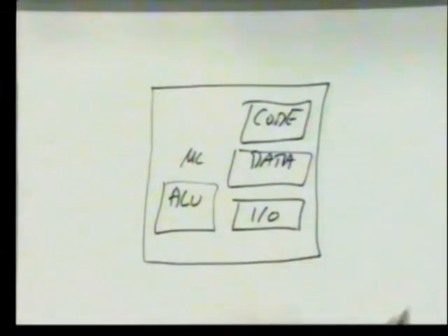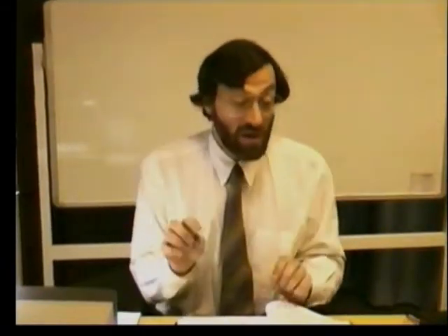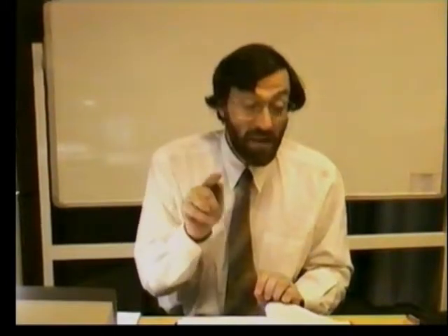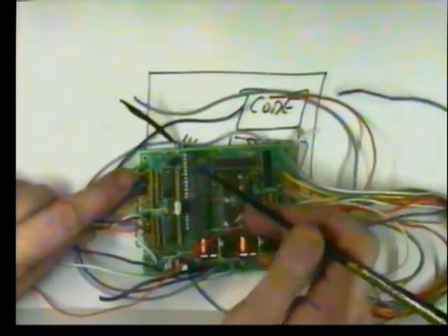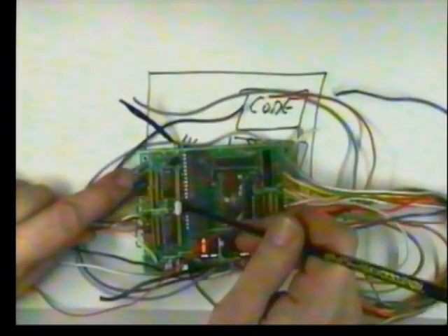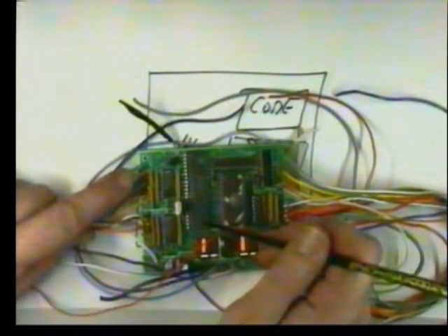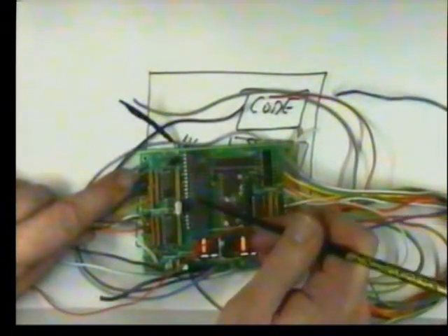The other thing I've said that they always have is I/O. That means that on the actual pins of the processor itself, there are memory mapped digital inputs that go straight into the memory of the processor. So I can take any of these boards we've seen in the past, and I can with quite clear honesty say, of these 40 pins on this device, 32 of them are memory mapped I/O.